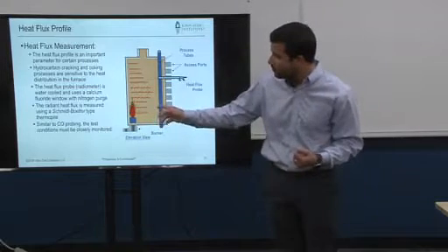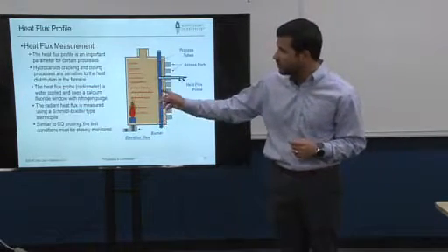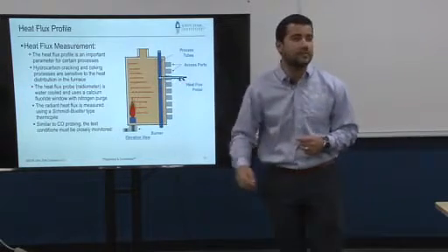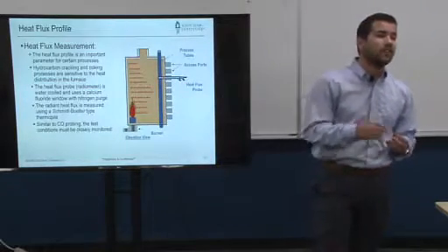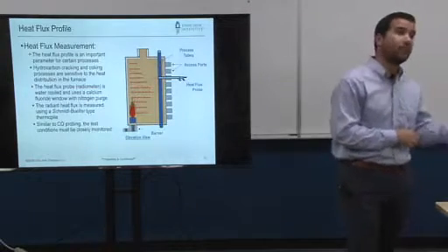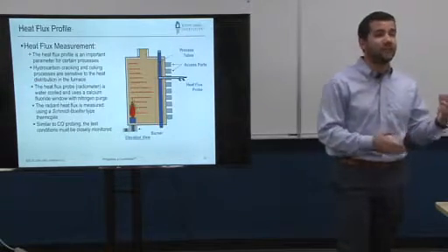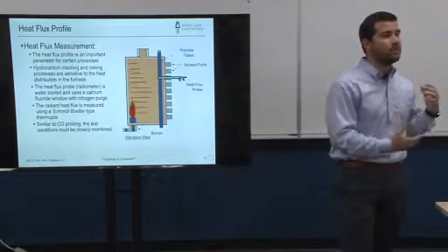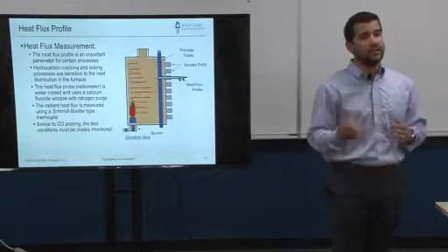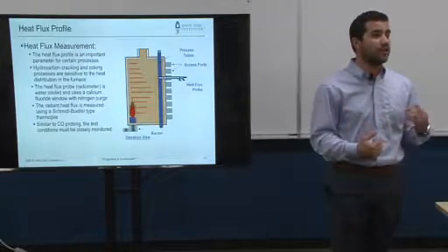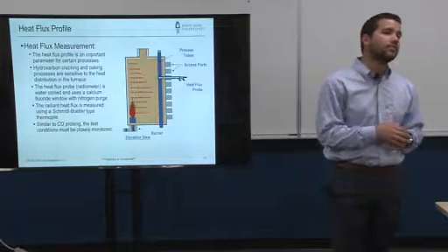You have like a little belly, if you will. You have a little curve. You start at a particular location, you hit a peak, and then it just dies back down. So there are some heater manufacturers, some process engineers in the heater world, that actually tailor that curve for a particular process. They present to us the curve that they desire, and then we get out there and make a flame shape or a burner design that would meet that given curve.